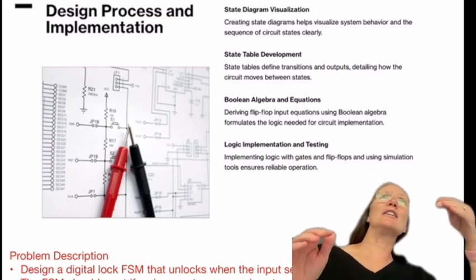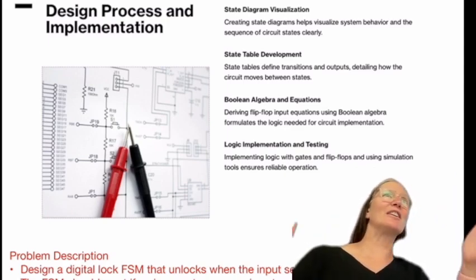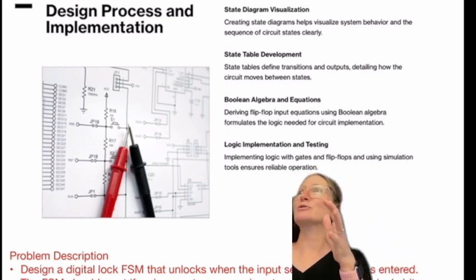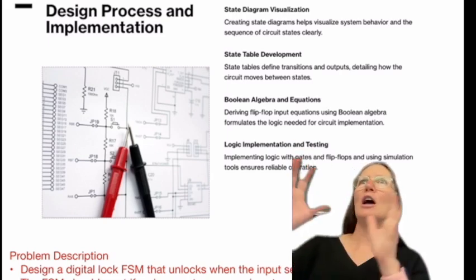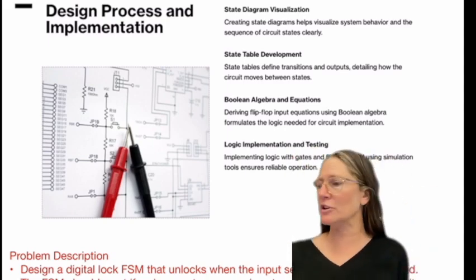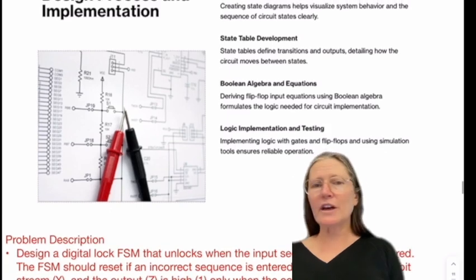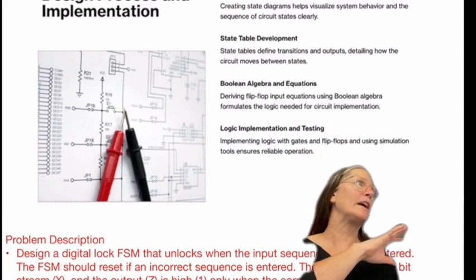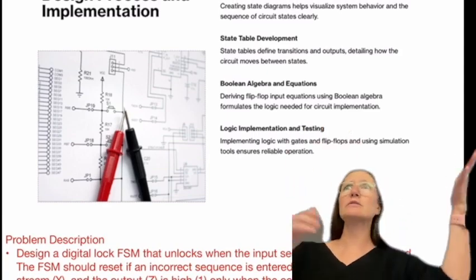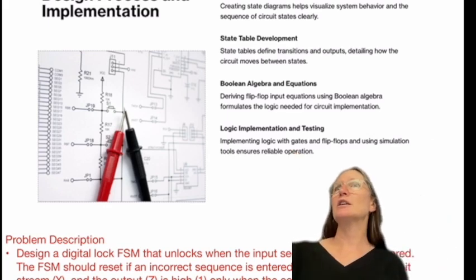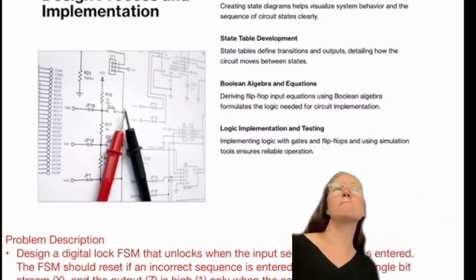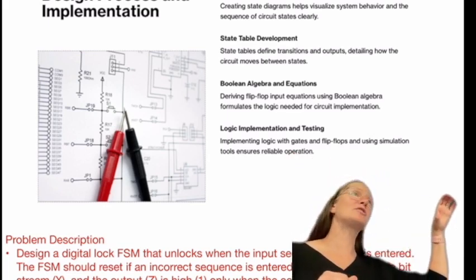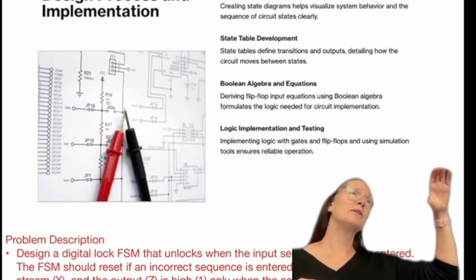It doesn't matter if you have the diagram, but I find it useful to visually see how things are flowing in a logic circuit. Once you get that table, then you're going to do the digital logic that we did for the LED light, where you identify the inputs, identify the outputs, and then do the combinational logic for that. The difference with sequential is there's one more step where you add in a flip-flop.